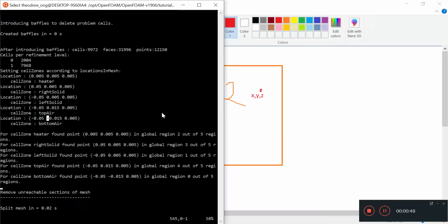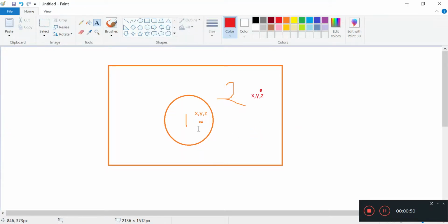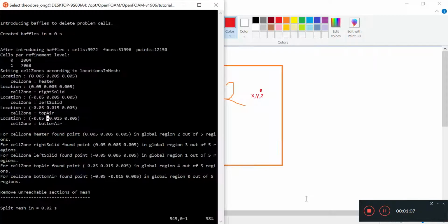So for example, I have region 1. This STL file encloses a surface there, and you need to provide an XYZ coordinate to say this is region 1. If you have the part outside region 1, we can call it region 2. You also need to provide an X, Y, and Z coordinate.